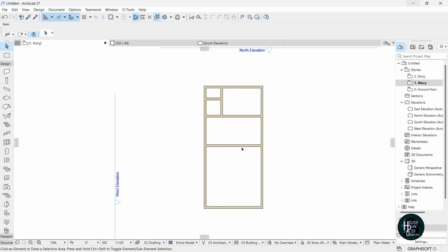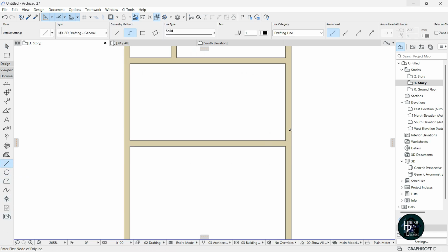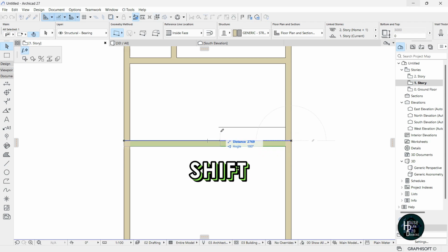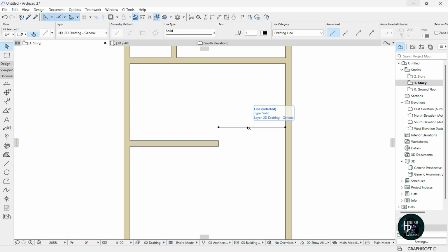Now the next thing I want us to do is come to the document section, click on the line tool here, click this edge here, stretch it like this and give a distance of 2.6. Click enter twice. Okay, click this edge here, click on this node, stretch it like this, hold down shift on your keyboard and click this line, press escape, click this line, click.